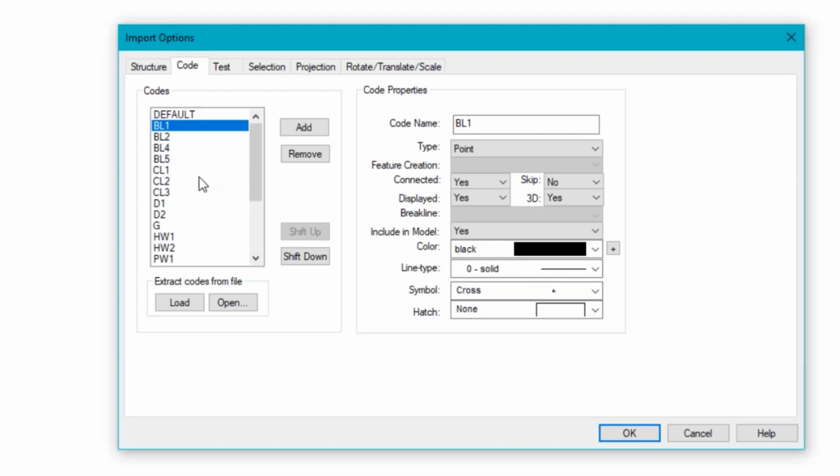And the way you handle it is, first of all, you make the BL feature into a polyline. Connect all by code works great, and that means that if I put in a wildcard here, BL star, I'll get a separate polyline for each BL. So connect all, but check the code to make sure that they match. And that will break the BL up into 4 segments. And now that I've created that, this one is not necessary anymore because it's handled by BL star. So the wildcard star handles anything that follows BL, and I'll just remove those.